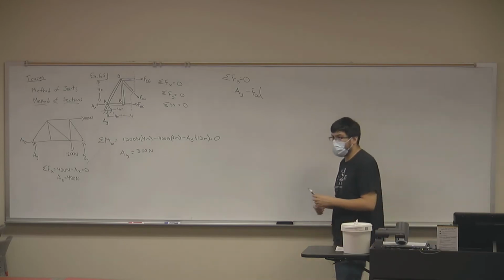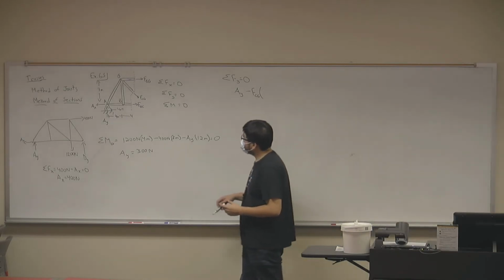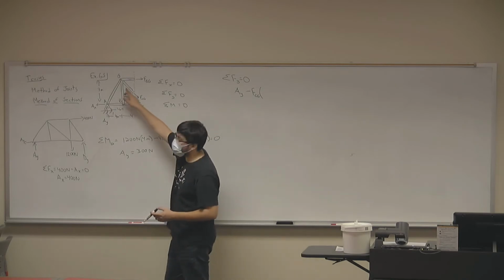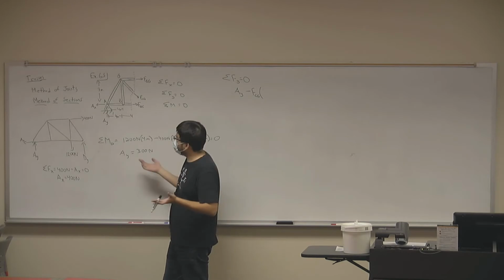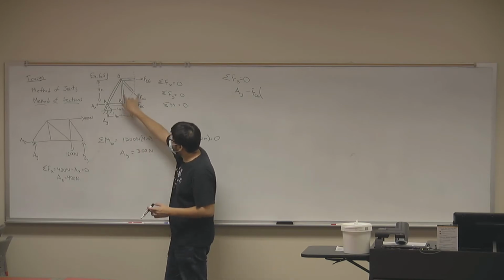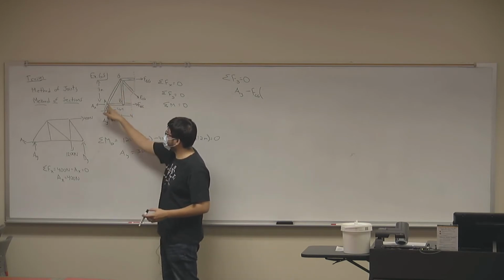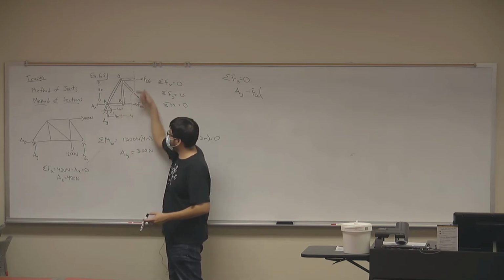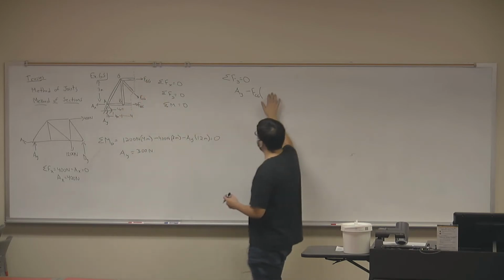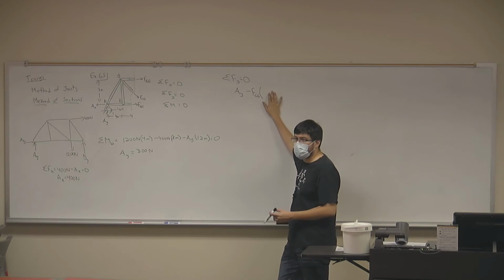What do you think, Will? It's okay. We're looking at the y component of this bar, FCG. Now we don't know the angle, but it's okay. We are told that in the horizontal, this has a 4 meter displacement. In the vertical, it has a 3 meter displacement. How can we find that slope that allows us to find the y component?